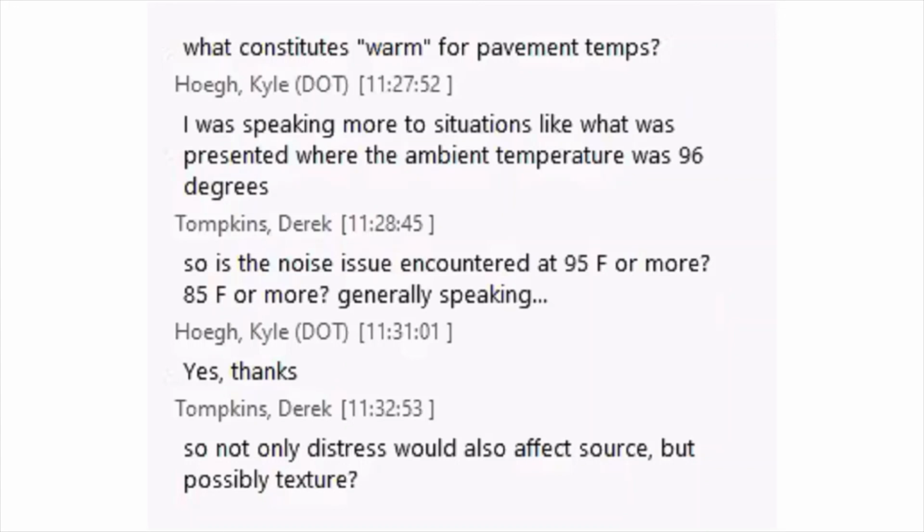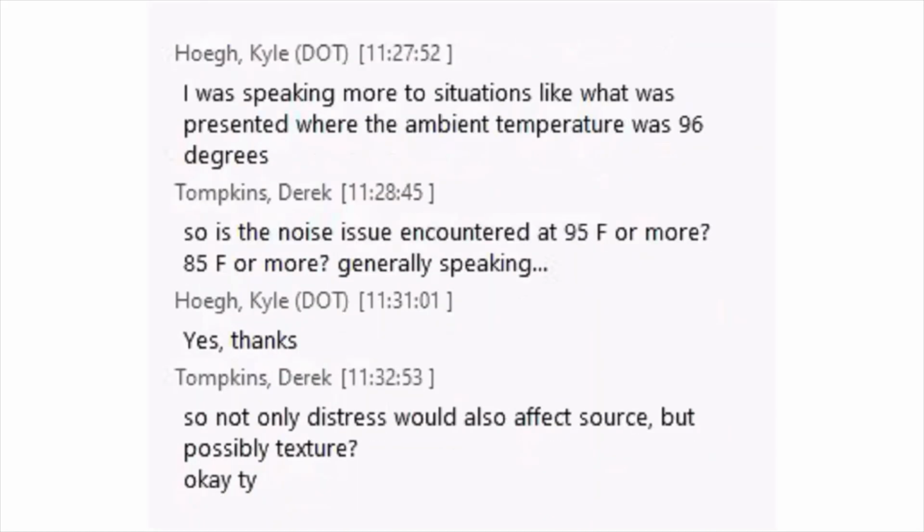So our approach is to do a lot of measurements so that we will get a lot of good measurements. But if we hit the bitumen when it's soft, we will not have good data. So it will depend on the roughness and the surface texture, how many stones you can see and how much bitumen is on the surface, probably. But we don't know much about that. We can see it in the testing we've done so far.